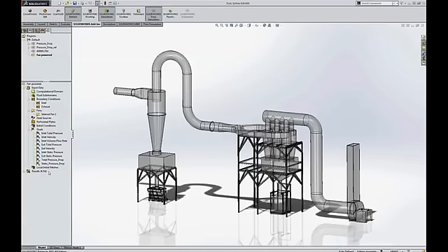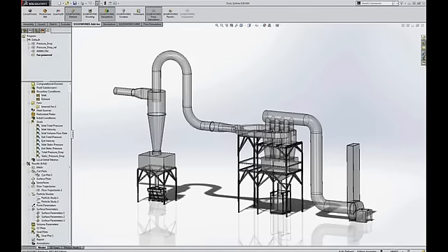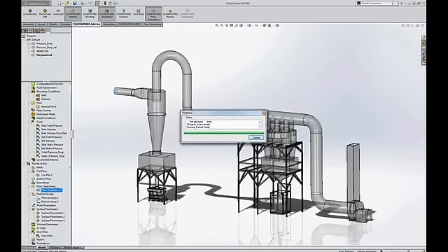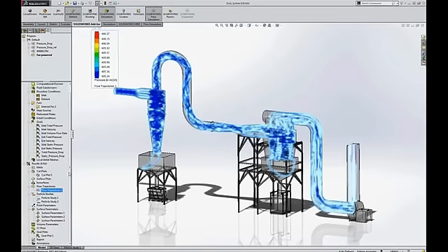So while we're getting questions, let's see, how do you validate simulation software? How do we know we get accurate simulation results using simulation? The question is with regards to validating the software. We actually have a series of NAFEMS standard tests. The best way to look at it is simulation really is a calculator. It's just an advanced calculator. So it's just doing mathematical operations behind the scenes. But we use these NAFEMS standard tests to verify that it's generating the correct results.